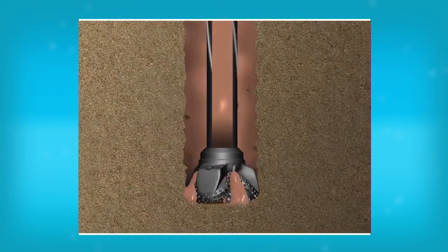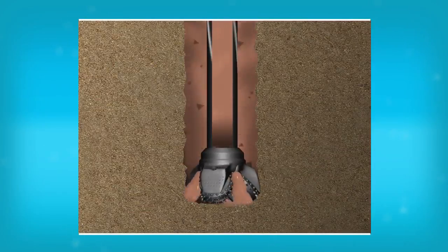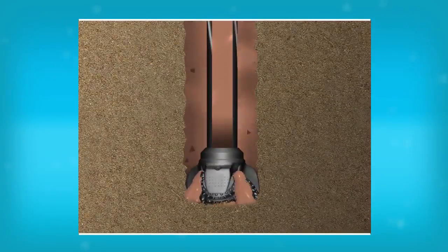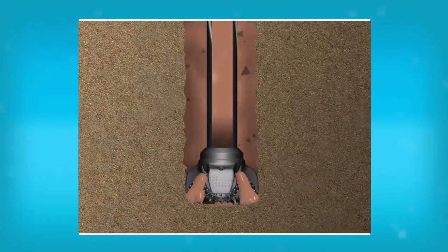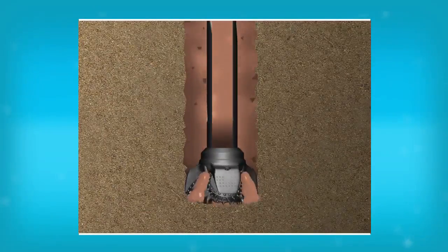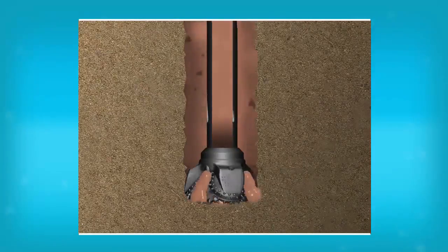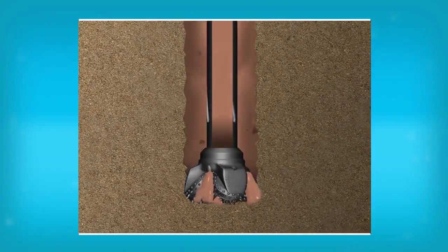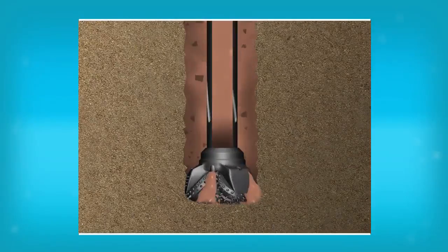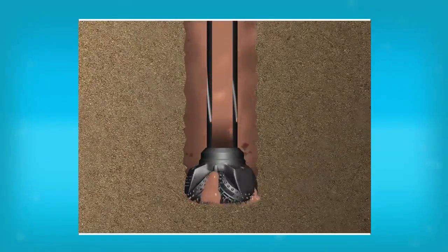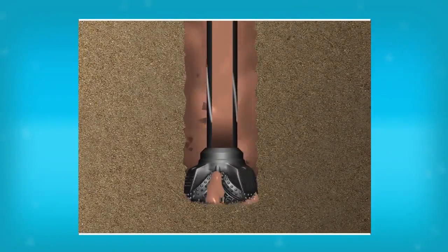The fluid being pumped by the mud pumps goes up through the standpipe manifold and down the drill string. Once it reaches the bottom of the drill string, it comes out through the jets on the drill bit and moves up the annulus, the area around the drill string. As it moves up, it holds the drilling cuttings in suspension and carries them up the annulus.